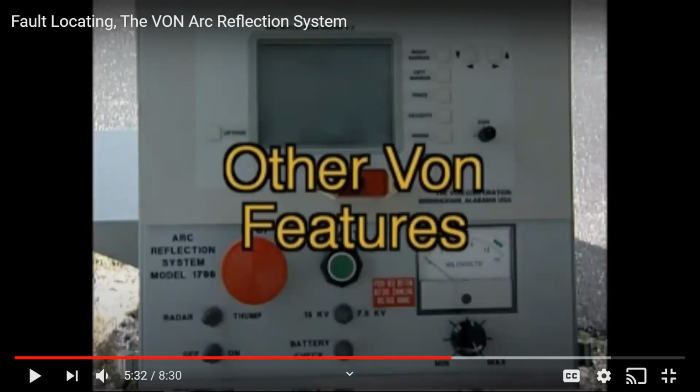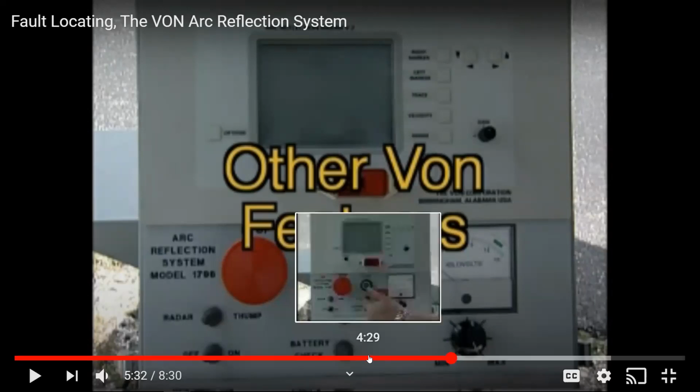Yes, sir. Okay. Once you hit the stop button, that is a feature of the piece of equipment right here, that it grounds itself inside the machine to that green wire that goes to the ground outside. But it is always a good idea to go ahead and reground it like you saw him do before, physically in front of you. The other part of this is here, and do you remember when the lid was open and it showed all the red and green writing in it? Yes, sir. Do the green stuff, you're good to go. Do the red stuff, you're going to break something.